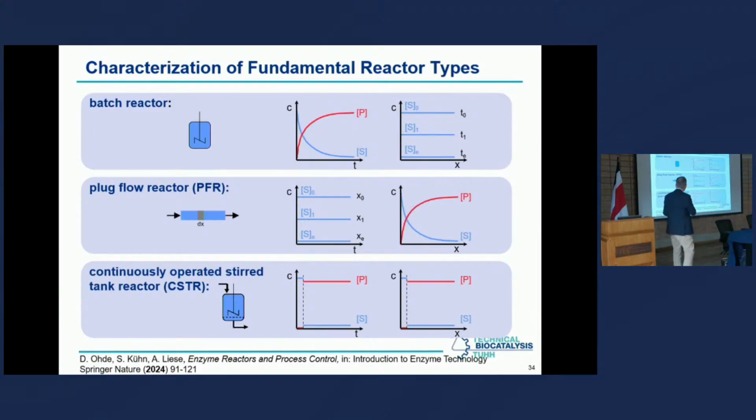In the continuously operated tank reactor, you're always at the top concentration of the product. And you're always at the minimum concentration of the starting material because this is well mixed. And if we pump through here, and let's assume this will take 1 hour to pump through this reactor, everything they add every minute is directly converted so that we are constantly at this high outflow condition.